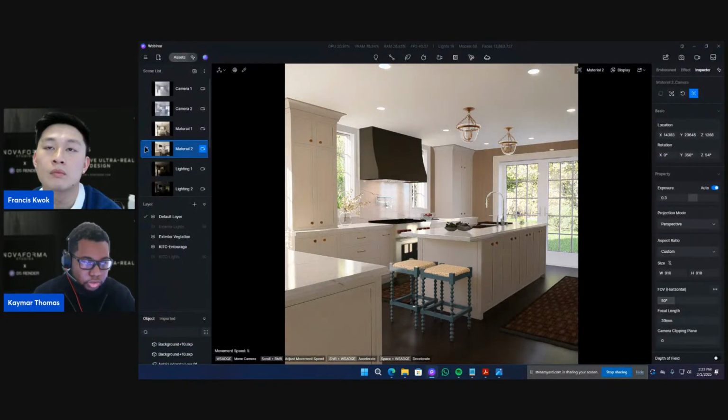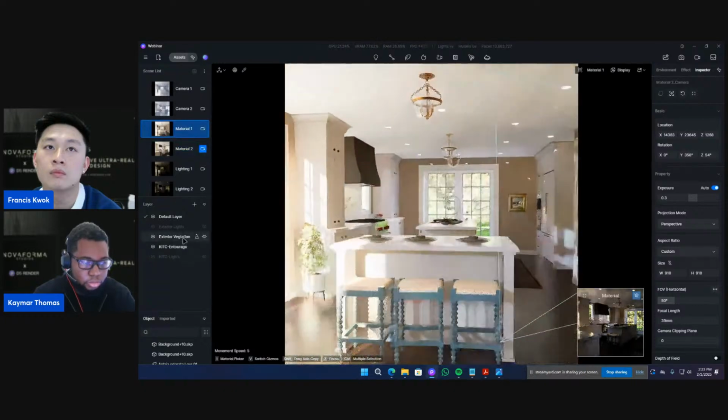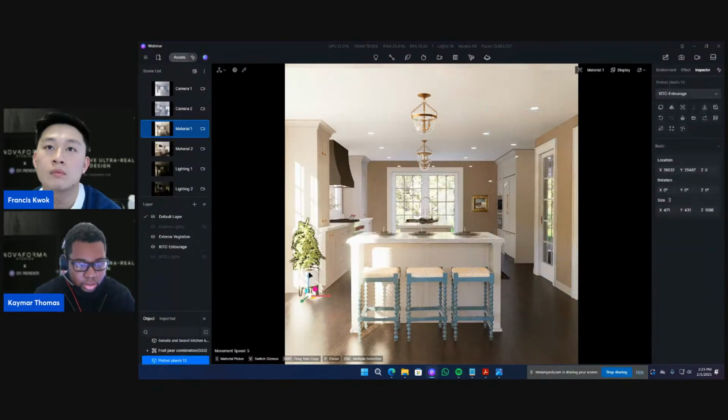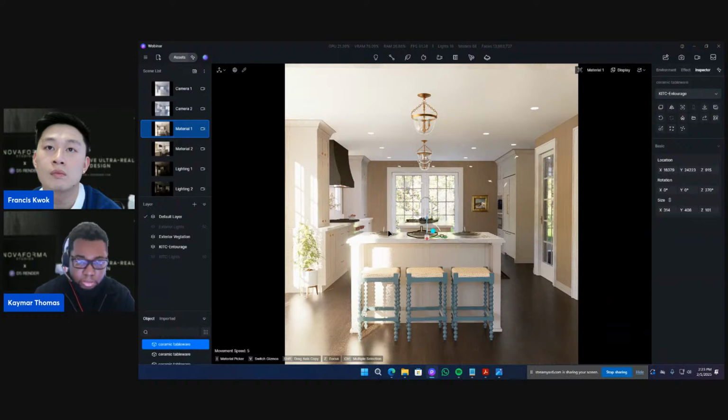So once you do your general passive material, you put in your entourage elements, things like planters, plates. These I would not recommend adding in SketchUp or Rhino into the overall model. I would just bring these in separately, because too much of these sometimes could bog down the model on the Rhino or SketchUp side.